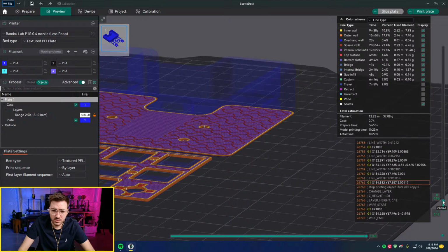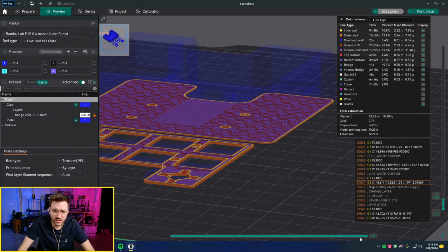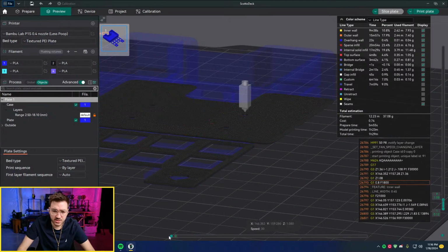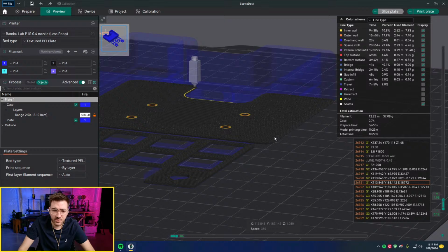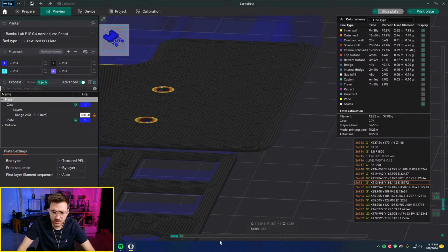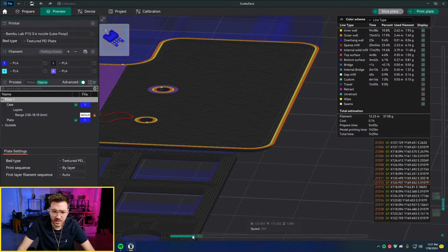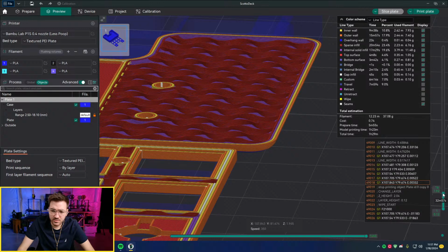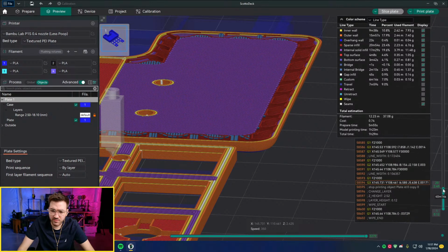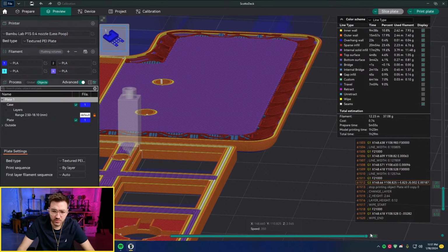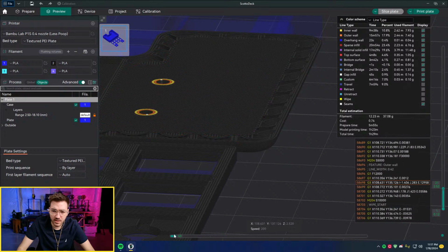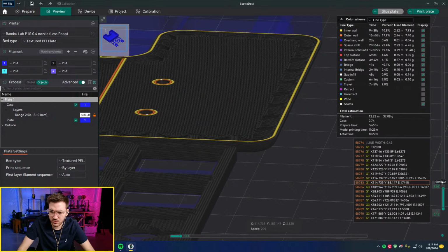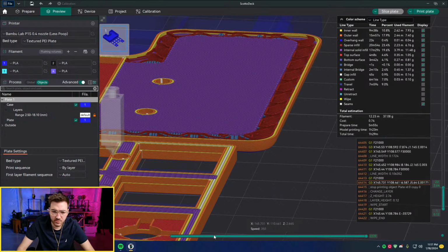not bad. But on these ones here, I want it to print the inner walls first. So you can see it comes to the inner wall and then it does the outer. Because these are overhangs, so that outer wall is an overhang while it's doing that little bevel on the bottom. If I did the outer first, it wouldn't actually print right, so it'd look really messy. But once I get to layer, what layer is that? It's 2.5. So right about here, it will switch to going outer, inner. So that one will do inner. Probably this next layer will do outer, inner.